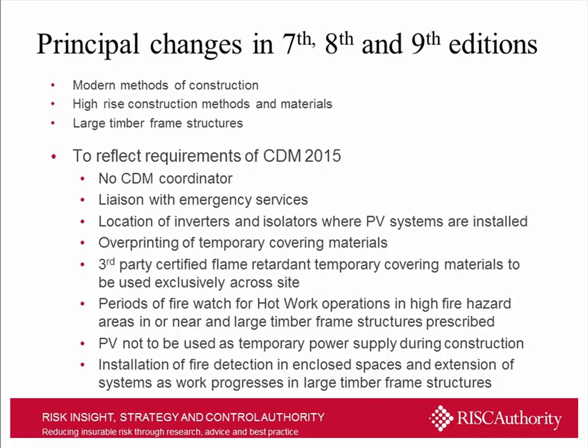In the 9th edition, the changes were principally undertaken to reflect the latest edition of the Construction Design and Management Regulations, which, to all intents and purposes, was tweaking requirements and responsibilities for contractors and designers. But we went on to tackle some other issues, such as liaison with the emergency services and strengthening that requirement, talking about issues associated with PV systems and the location of inverters and isolators. The overprinting of temporary covering materials.